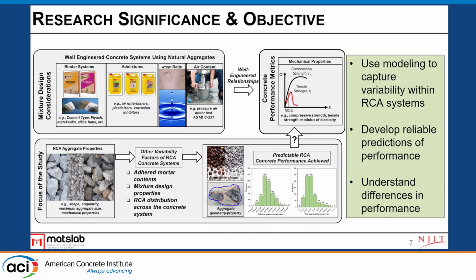So because of this, we need to use modeling to expand our capabilities to look at those, because when we use modeling, we can theoretically orient an aggregate in any direction we want. We can put the adhered mortar in any place that we want, and so we can start to look at